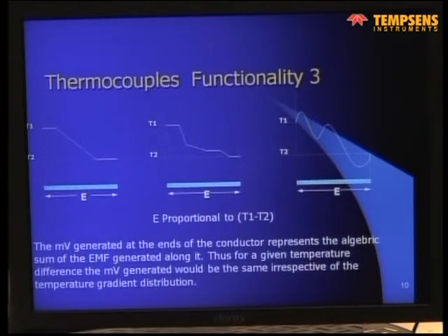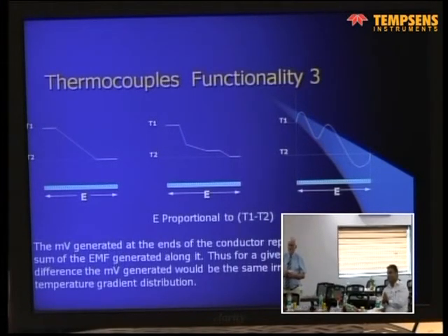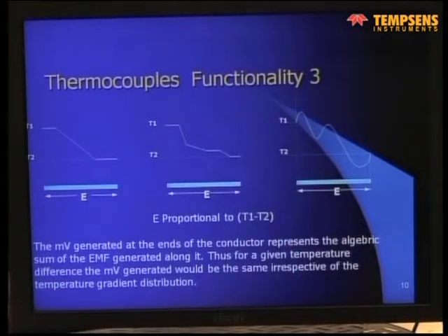Second thing is, the thermocouple will not end at the head. So you have to use an extension, compensating, or thermocouple cable to your apparatus, which is measuring the temperature, where you can do the cold junction compensation. That's the basic thing. All the hardware between the hot tip and the input terminals of your measuring device, meter or transmitter, has an effect on the temperature measurement with thermocouples. All between, cable included.